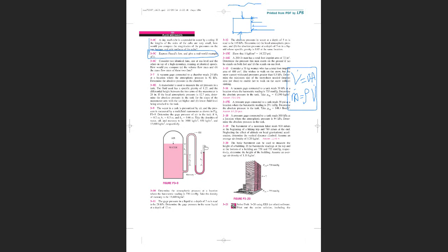You are absolutely right. The volume flow rate will be the same. There is no H in the equation. The cross-sectional area is the same and the velocity is the same. The issue is the mass flow rate, because the density at sea level and at very high mountains will vary, if you agree with me. And that brings a variation in the mass flow rate. That is the point. Moving forward.